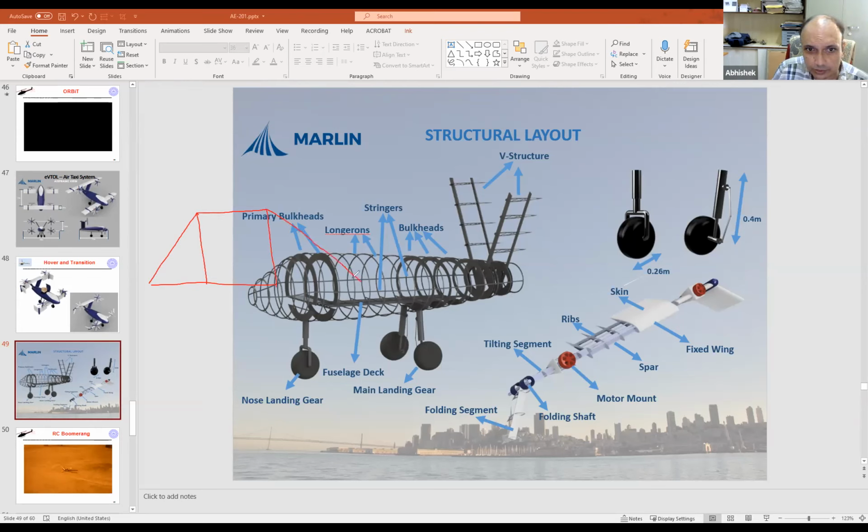Even bridges, actually. You would have seen a lot of bridges which are supported by these trusses. These trusses have uniaxial members which can only take tension or compression. You can imagine these small rods which are connected together. They will all be connected through pin joints. So all these points will actually be pin joints.